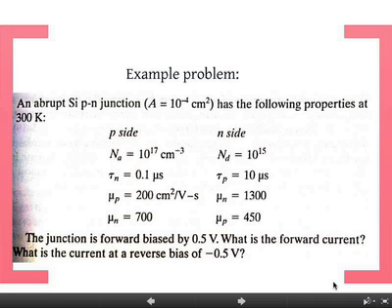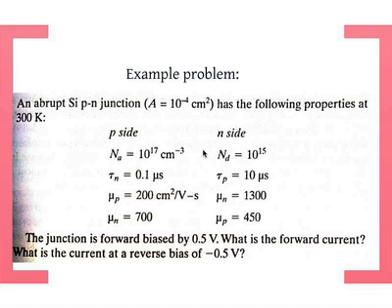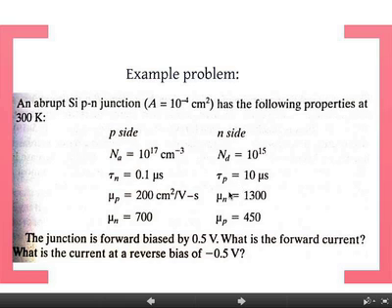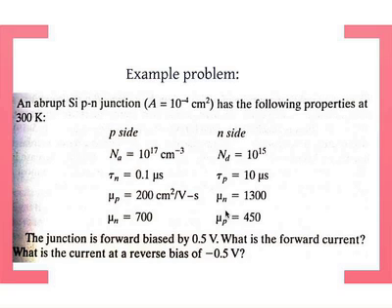By the way, you can see it's not really a P plus N junction. It's only 2 orders of magnitude different, right? It's not a great diode from that perspective. And you can see the big difference in the mobilities and so on, right? The mu P here is twice as much as that. The mu N here is twice as much as that, which suggests that there are 2 different materials and so on. So these kinds of things are what you actually make in your diode, right?